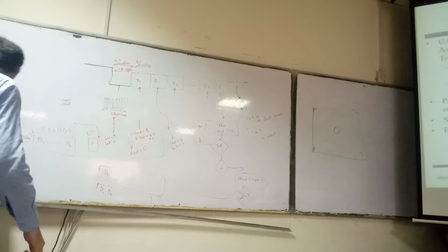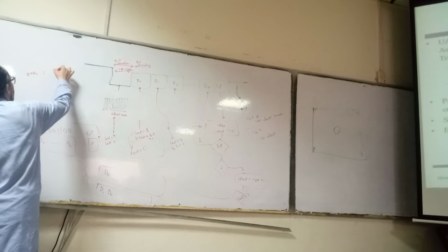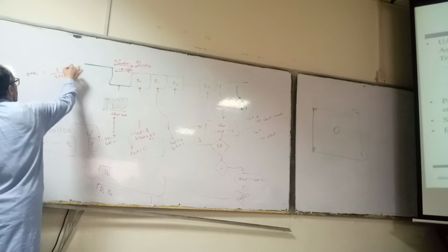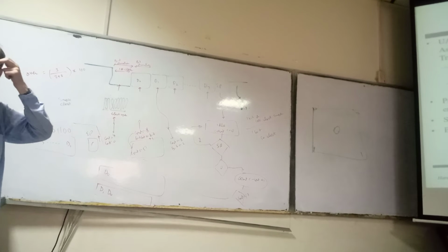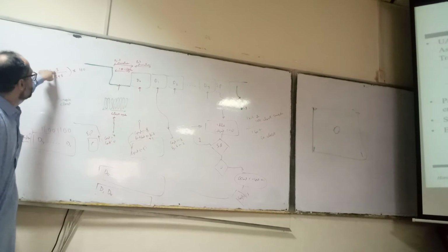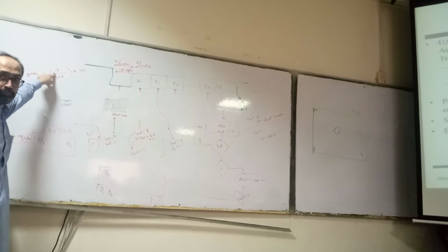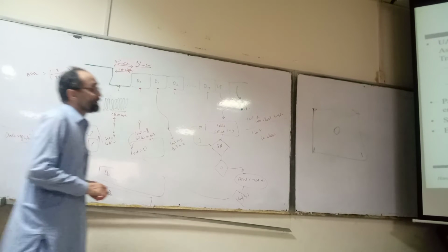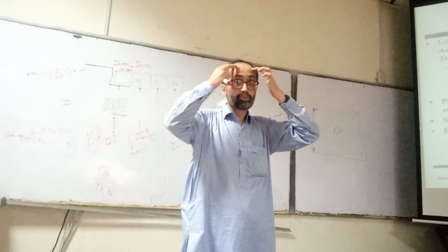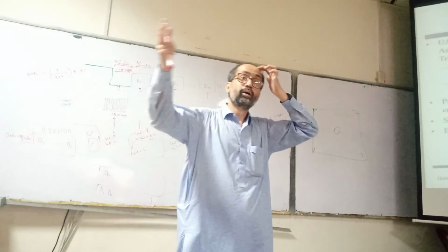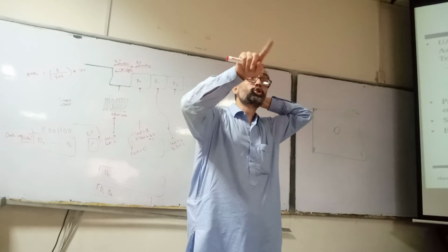So in this case, the overhead is actually 3 divided by 3 plus 8, multiplied by 100. Why are 3 bits used? One for the start bit, one for the stop bit, and one for the parity. Now in this case we have assumed that we are using a parity bit. The parity bit can be even parity or odd parity, and it can be used to detect the error.